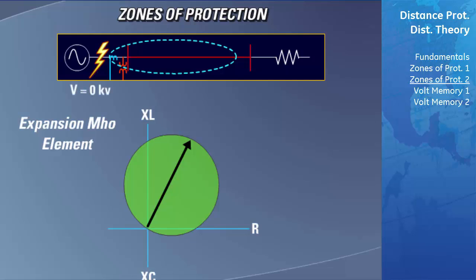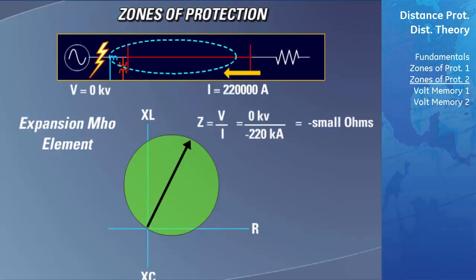If a fault occurs just before the beginning of the transmission line, and the transmission line is double-ended or multi-ended, current will flow into the CT from the opposite direction. If the D60 now calculates the impedance of the line, the value will be negative, and plotting that impedance point will put it very near the origin, but in the reverse direction to the transmission line.